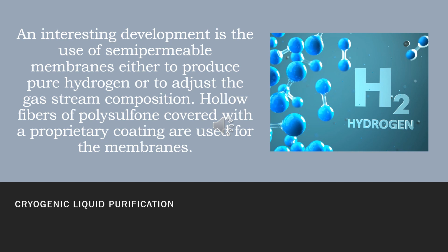The modules can be run in series or parallel to attain high purities or to vary the composition of synthesis gas. One application is the production of 1.3/1 hydrogen to CO gas for oxo alcohol manufacture from 3.1/1 hydrogen to CO gas.